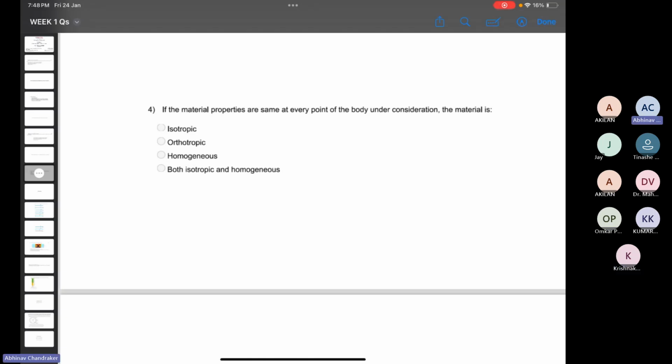Okay. So when we are saying isotropic, it's a more general property. Isotropy or anisotropy is a more general property for any material. In one case, the material could be a fiber reinforced composite, where you have very strong fibers in a matrix. There you will have directional properties, as I told a few minutes ago when I was talking about isotropy, and it will always be some kind of anisotropy. But isotropy is the most ideal condition, where in every direction the material will behave exactly the same.